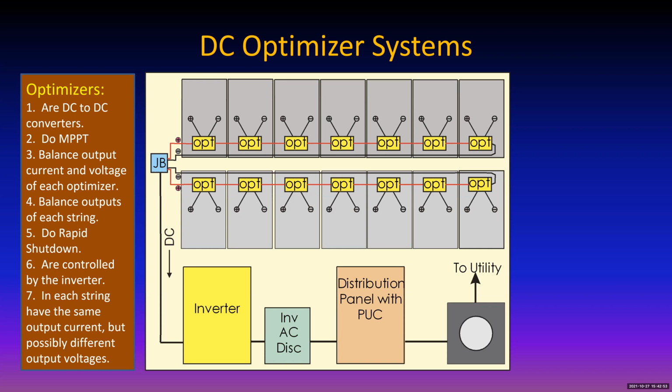Some manufacturers will probably be signing various agreements that you can use my inverter with your optimizer or vice versa. But if you want to be safe, it's a pretty good idea at this point to use one manufacturer's product. If you choose a particular inverter, it's better to choose the optimizer of the same manufacturer.